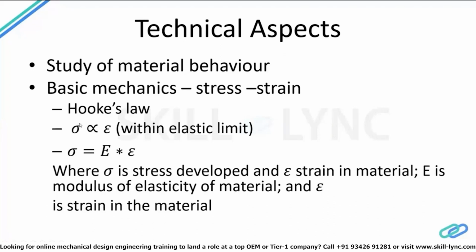So stress developed in a structure is directly proportional to the strain, which is epsilon here. And this linear proportionality is valid only within the elastic limit of the material. Beyond that, it's going to be in an inelastic zone, and we are going to take a look at that in the next slide. So this is the basic principle that we always need to be aware of whenever we are working on a structural engineering analysis. Whenever there is deformation, there will be stress developed in the material, and therefore in the member.